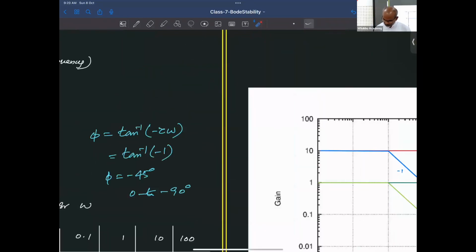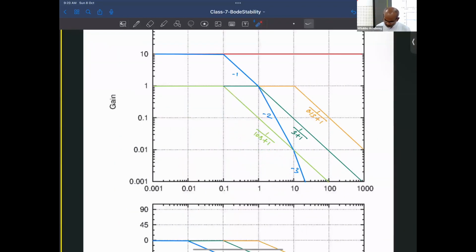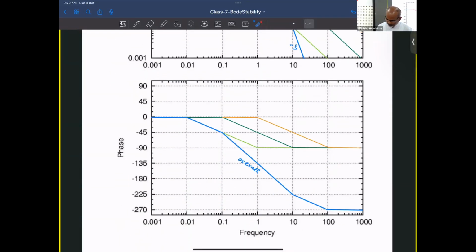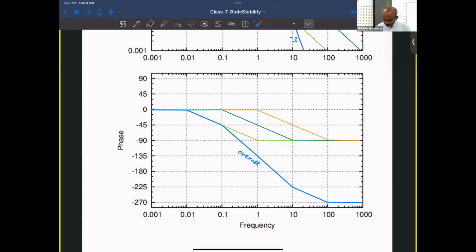In that way only this line is plotted. I have this overlapping blue line, which is the overall plot. I will assume this line is extending here. Here the corner frequency is 0.1, 1/10 of it starts here, and 10 times is here. So this is simply a nice straight line, which is approximate. Otherwise, it will be going like this, with some deviations at the endpoints.